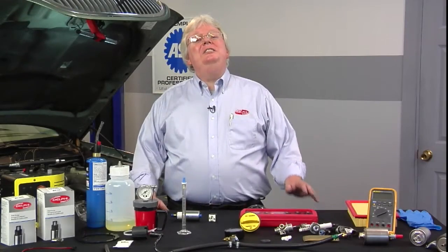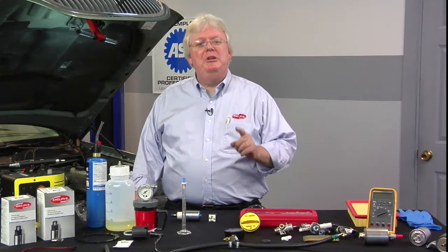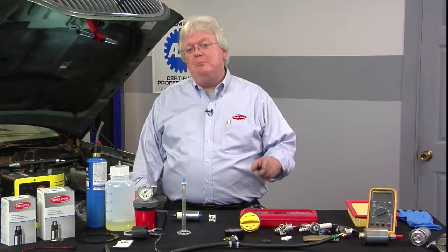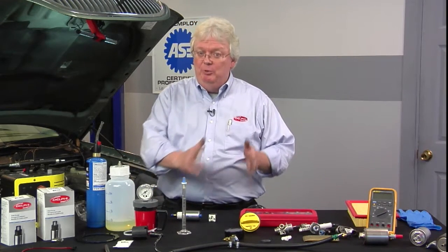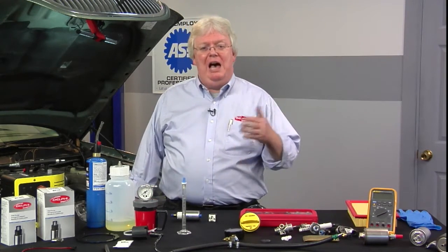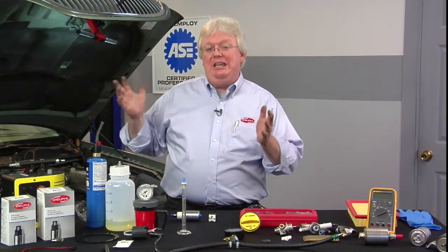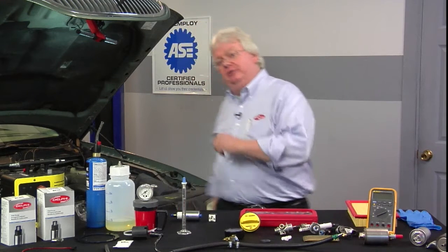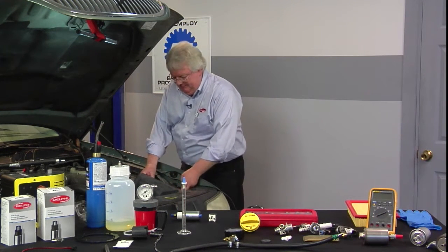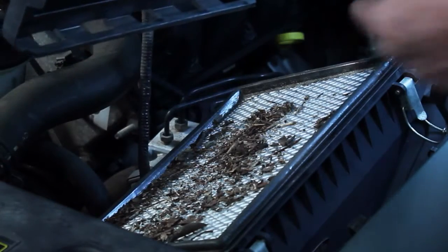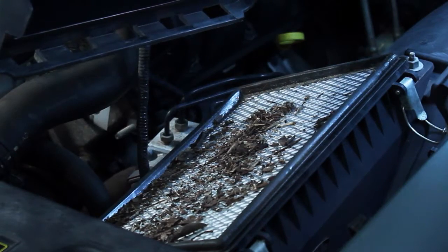Well, let's go take a look and see if maybe we have a lack of air due to a restricted air filter causing this base pulse width to be modified by the negative fuel trim numbers. We're running rich, so we're compensating with a negative fuel trim number, meaning we're taking pulse width out of the equation. Let's look at this air filter. I wonder if they've changed it lately. Oh my gosh, look what we got here. We may have pay dirt, no pun intended.